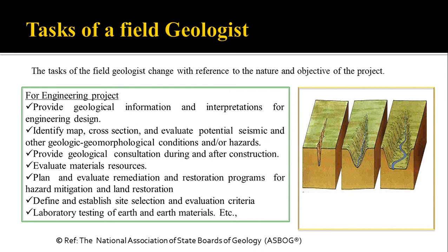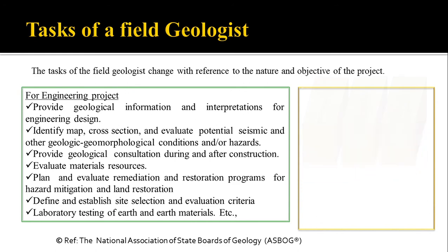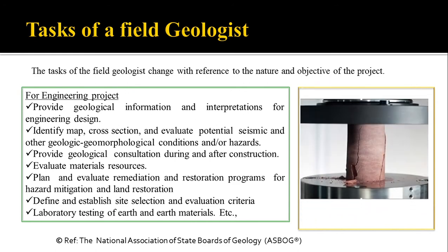Not only that, the laboratory testing of the earth materials is also done by the geologist. The rocks have to be taken from the field and tested in the lab, to find out whether the rock can hold the amount of pressure which is given to it by the dam.